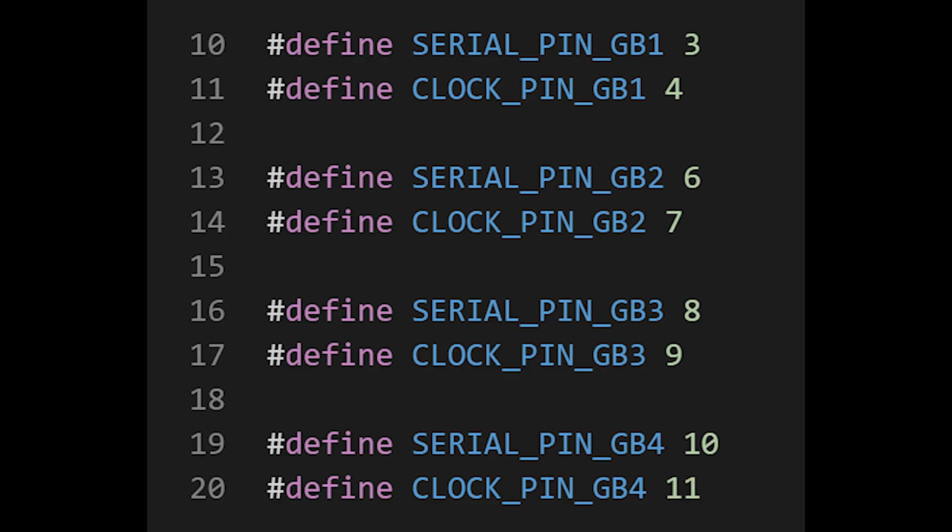Next, we'll need to figure out the way in which we assign the signals of a MIDI channel to its own APU generator. For each channel, we'll need both a value to represent its intended target generator, as well as a value to designate its intended target Game Boy. To send out the signals of a Game Boy via the correct GPIO pins, we'll obviously always need to know the position of the correct serial in and clock pins.